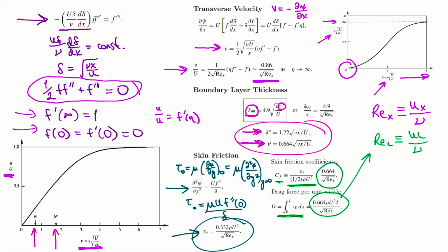That equation actually shows that the drag force is proportional to the 3/2 power of velocity. And this we can compare to the low Reynolds number flows, where the drag was proportional to the first power of velocity, right? We write the overall drag coefficient, and we scale that, as I'm showing on the bottom right here, as we normally do, to get this expression.